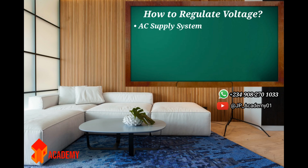The sixth method is the use of series capacitors, and these are used in long extra high voltage transmission lines. The seventh method is switching in shunt reactors during light loading or while energizing long extra high voltage lines.